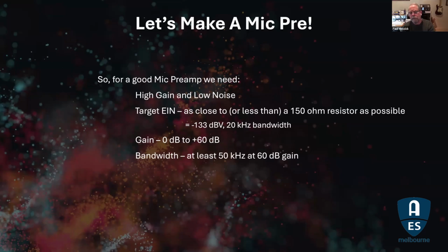We need some bandwidth. I'm shooting for at least 50 kilohertz here at a gain of 60 dB. You might say, well, why go more than 20 kilohertz? Because most of us can't hear much above 8 kilohertz anymore. What do you need 50 kilohertz for?